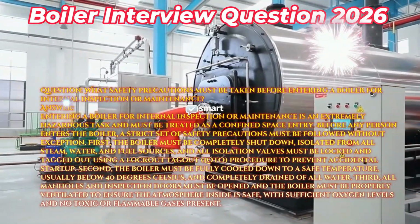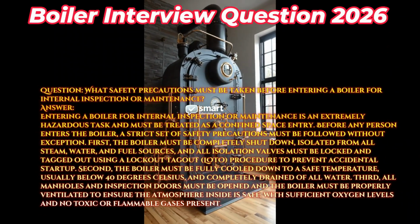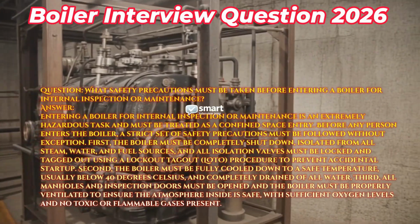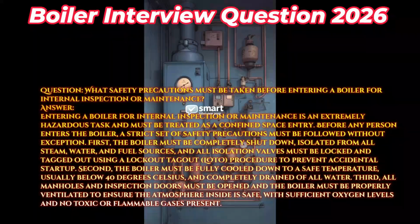Question: what safety precautions must be taken before entering a boiler for internal inspection or maintenance? Answer: entering a boiler for internal inspection or maintenance is an extremely hazardous task and must be treated as a confined space entry. Before any person enters the boiler, a strict set of safety precautions must be followed without exception.